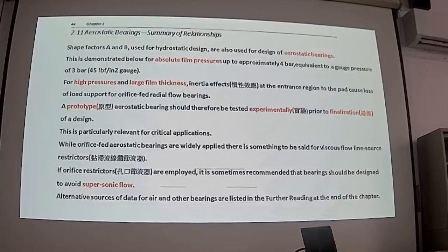That is because usually the air bearings are small in size or in dimensions, and usually it's very difficult to install the capillary restrictor inside the bearing. Therefore, in most of the case they are using the orifice restrictor instead of the capillary restrictor.